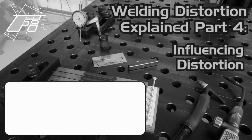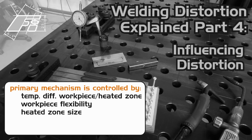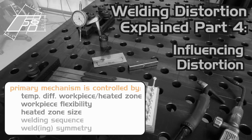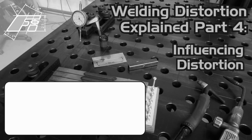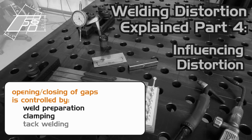As you'll see from the following, the primary mechanism of welding distortion is controlled by temperature difference between workpiece and heated zone, by workpiece flexibility, and by heated zone size. Furthermore, to control distortion, the heated zone can be influenced with welding sequence and weld symmetry. As already mentioned, a secondary mechanism of distortion is the opening and closing of gaps. We control this particularly with weld preparation, clamping, and with tack welding.